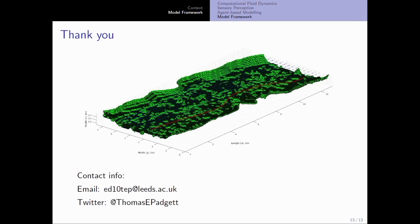I'm confused. So your fish size is less than the mesh size, right? No, a fish is about 4 cells long, about 4 CFD cells long. So your one-way coupling assumption is not that valid in this case, is it? How so? Because there's a solid boundary in your flow which disturbs the fluid.